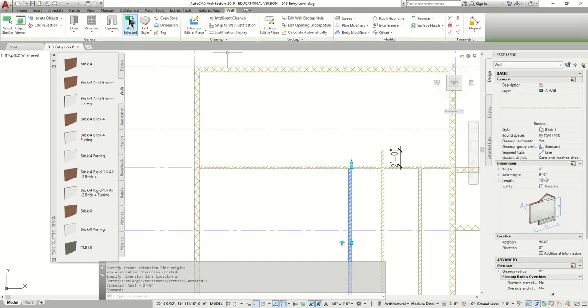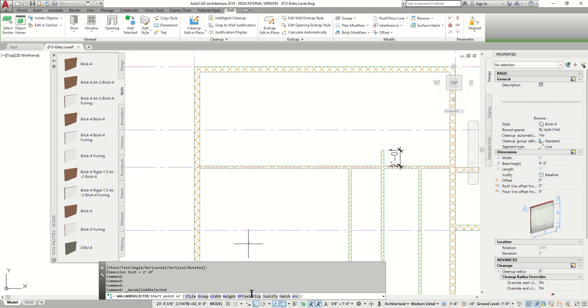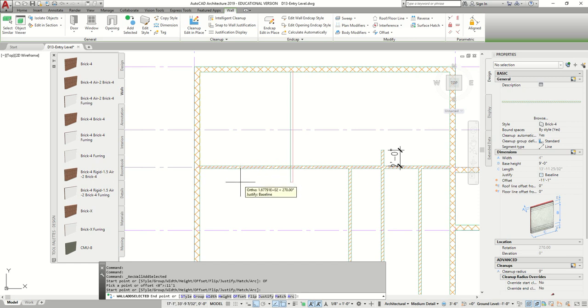So click this wall here, go back to add selected, and we're going to do the same object we did before, offset, and our offset's going to be, what's the distance here, guys? It should be 11'1". 11'1" is our distance from this corner here, and we're going to go downward until we hit it's a random number, 5 foot. We can change it afterwards. 5'9" dash 5/8.